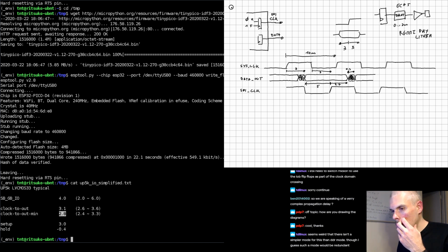There is support for pushing data through a single PMOD using DDR data, and I use a 90-degree out of phase clock generated by the PLL to do that. So the I/O that's generating the clock signal to the HUB75 panels isn't clocked from the same clock as the data bits. It's clocked by a clock that's 90 degrees out of phase, right?